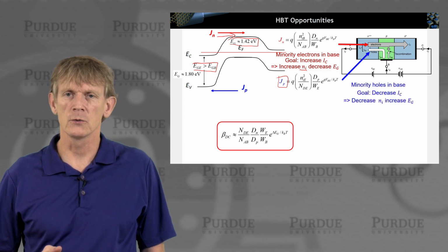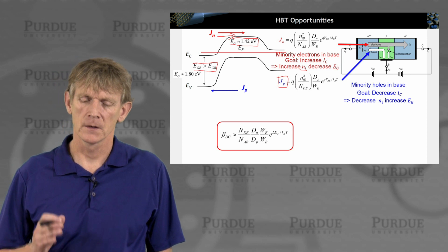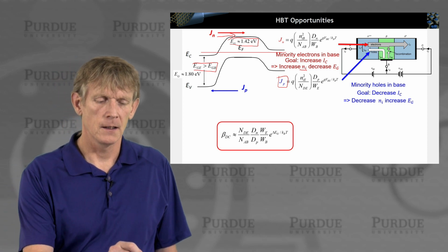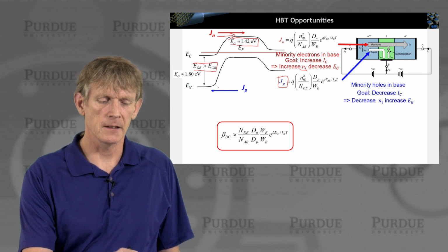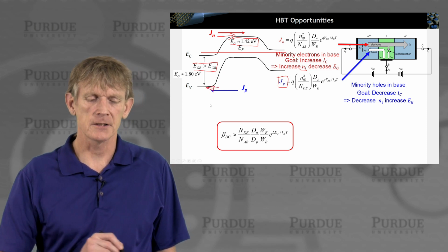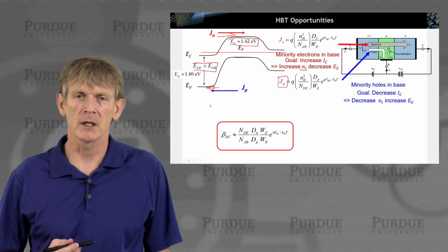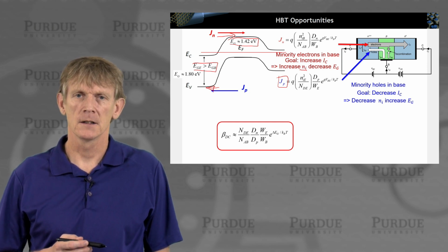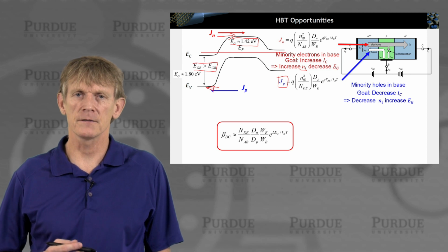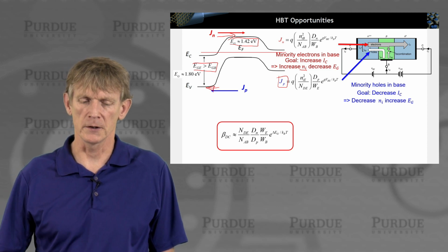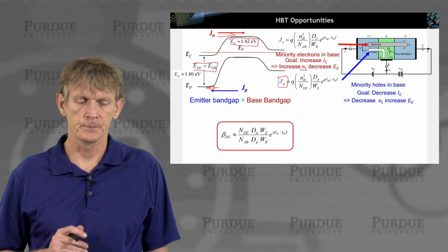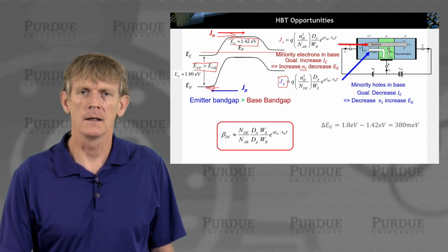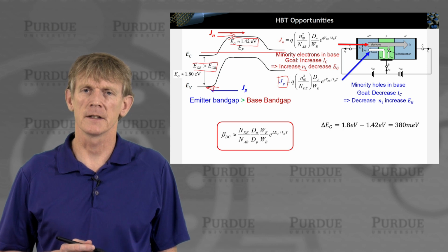And you want to reduce the hole current, okay? So this is all good, right? You're making a much bigger rejection, making it much harder for hole current to flow, and you keep it easy enough for the electrons to flow forward. But what does that buy you? Okay, here's the argument: the band gap in the emitter should be greater than in the base.